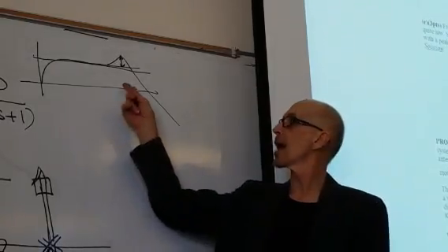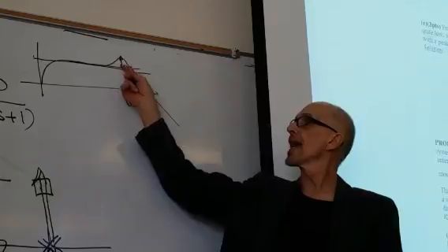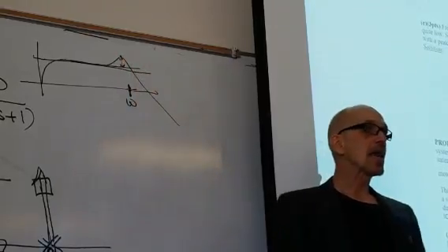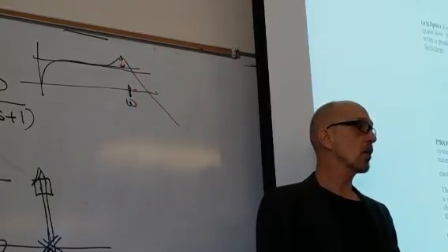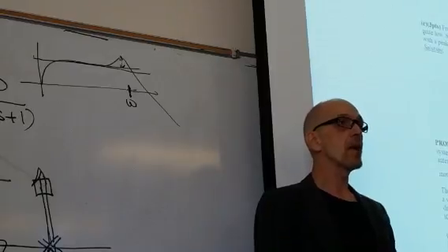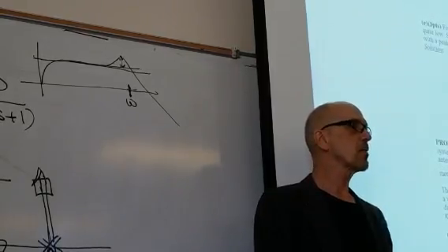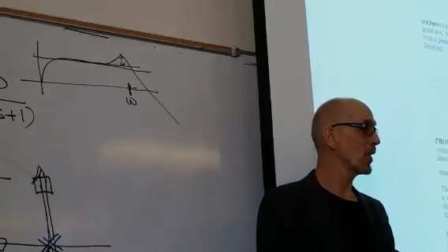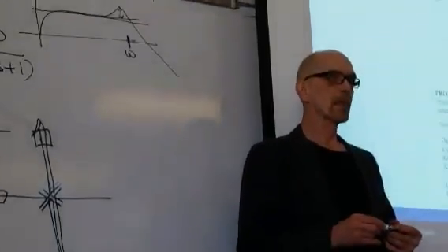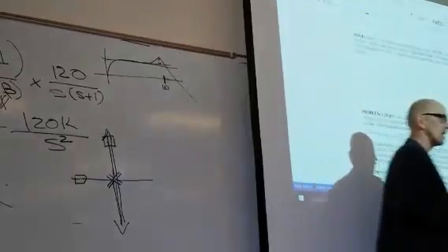And if you operate up here, it's going to amplify that many dB and tell you you've got an acceleration which is maybe 50 times greater than what it really is. Because you're not measuring acceleration, you're measuring the resonance of the accelerometer. Okay, so that's kind of a semi-obtuse point.